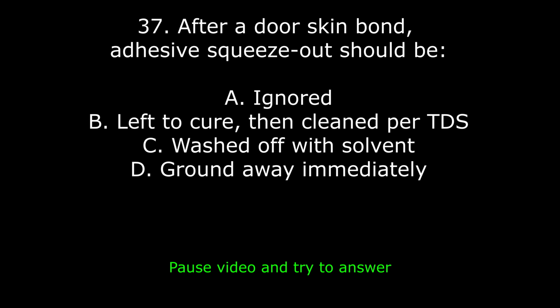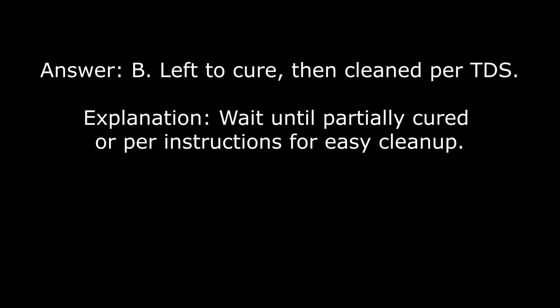37. After a door skin bond, adhesive squeeze-out should be A. Ignored. B. Left to cure, then cleaned per TDS. C. Washed off with solvent. D. Ground away immediately. Answer: B. Left to cure, then cleaned per TDS. Wait until partially cured or per instructions for easy cleanup.